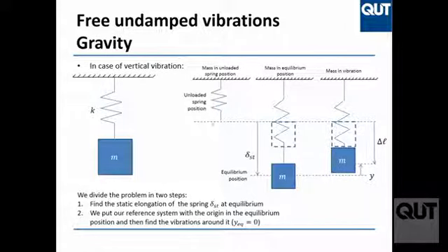And it goes into here. This is the equilibrium position. When I said vibration happens around the equilibrium position, I meant that now the system starts vibrating around this point, up and down from here, not from here. Clear? In horizontal position, it doesn't make any difference because there's no initial elongation if the vibration is horizontal. But if it's vertical, gravity will move your equilibrium position down.